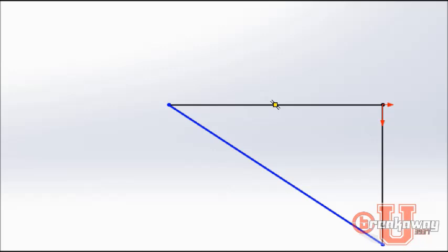To be honest with you, I don't mess with these very much. They're a little bit difficult to work with. You're looking at it in a coordinate sense. I go up here to what's called Smart Dimensions, and I click on Smart Dimensions. Now what Smart Dimensions does for you is it helps you to create a segment or length depending on what you want, and it helps you to set a parameter to it.